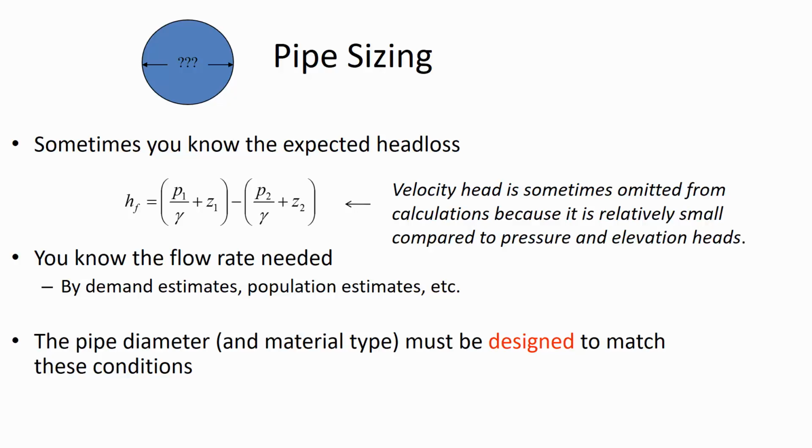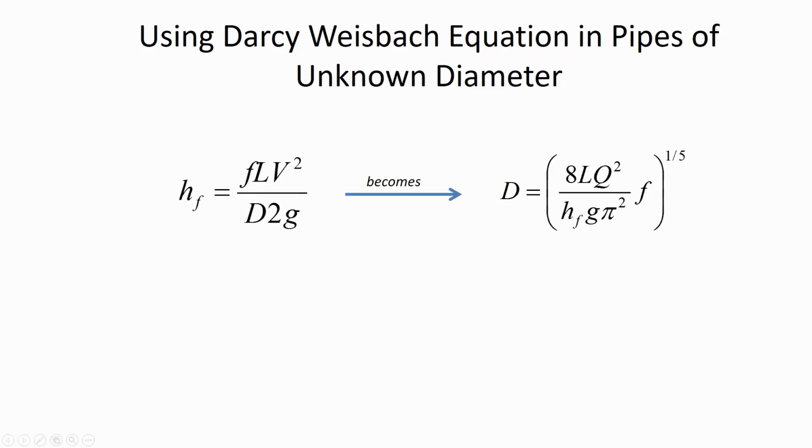And the pipe network sizing is always juggling how much pressure you've got at a certain location versus the pipe size. And if you make the pipe size smaller, then you're going to be reducing how much pressure there is at a location. And so here, this idea of finding the required diameter is going to be matching ever smaller pipe diameters until you have the head loss that matches those flow conditions. So the difference between design and analysis is in design you're optimizing and you're iterating over and over again until you have the ideal pipe diameter that gives you exactly the amount of head loss you can tolerate.